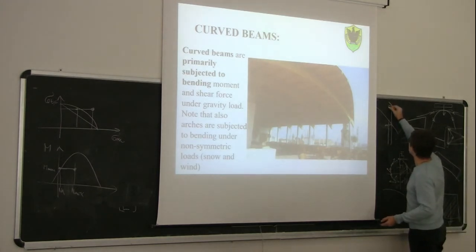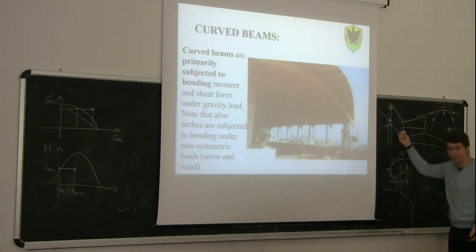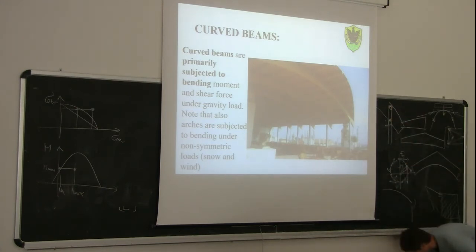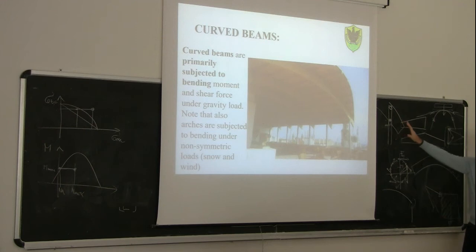It should reach up to here in order to take the compression and tension that you have on the upper and lower sides, right? So only this one could be a fixed connection, a rigid connection. But since it instead finishes here, it's an internal pin connection.